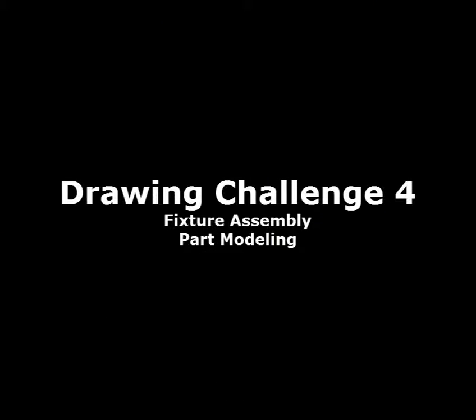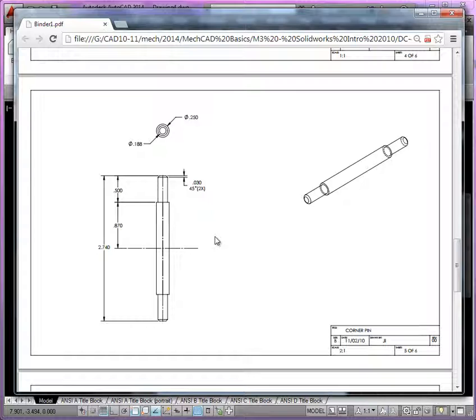Alright, so now we're going to take a look at the corner pin here. And this is a model where, if you take a look, we have symmetry, and also, if you look even closer, we have the symmetry revolved around the axis, right? So if we just take a look at 1/4 of our solid here, we can produce the profile that, if we revolve and then mirror, we'll be able to produce the entire corner pin. Let's take a look at how we do that.